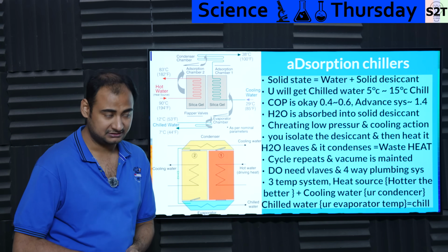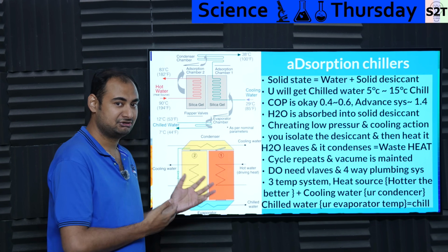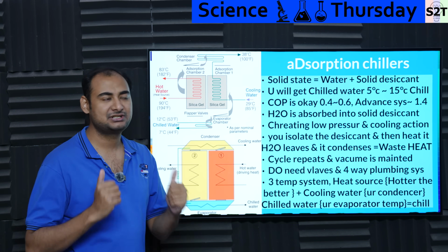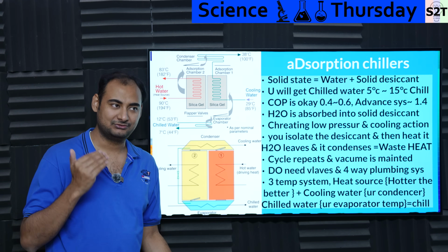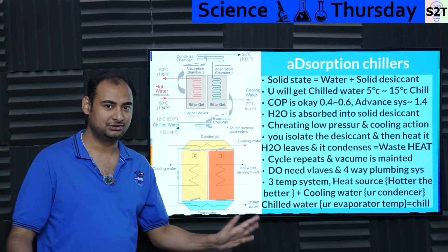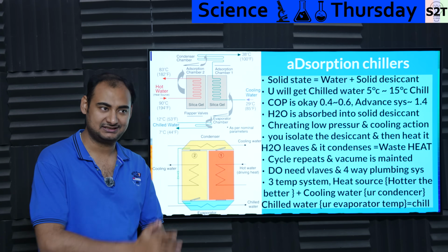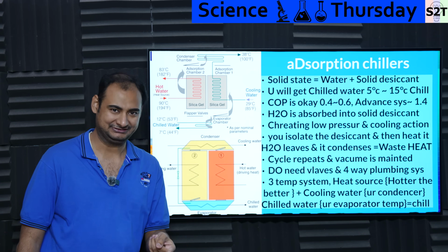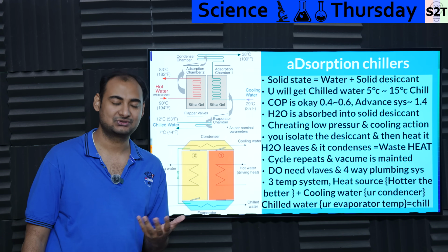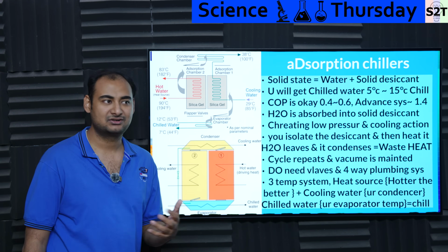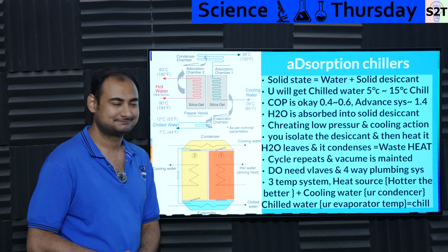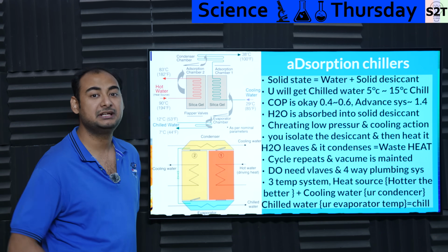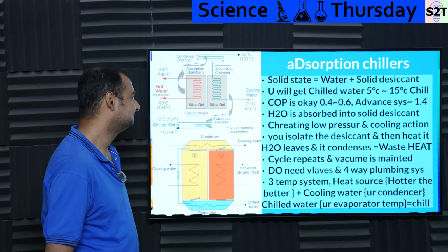Now, is that sufficient? Here's the deal. Places where I'm thinking about utilizing that, we're going to be cooked. So 15 degrees Celsius is good. Any temperature that is below dew point temperature will remove humidity from the air. We're good, we do not need more than that. Like if you have nothing else, if you just have this system, we're good. And again, we do run this sort of system, so we know that a fan coil unit does not require minus 10 degrees Celsius water. We find with 15 degrees Celsius, it will still dehumidify. Again, it will be slower, but it will work.